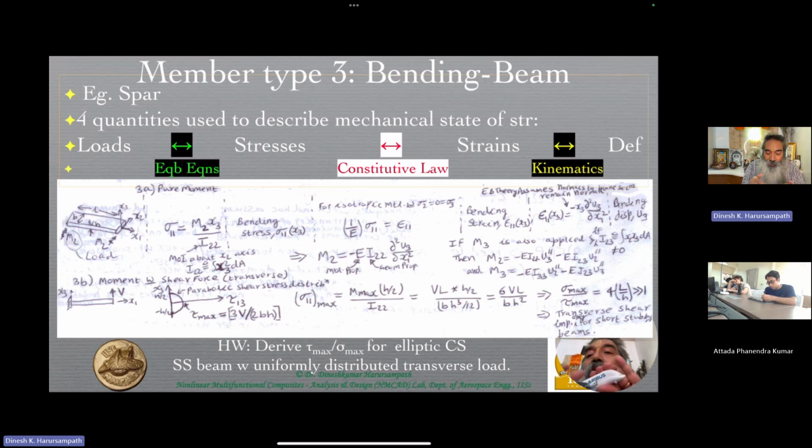And so you will have, of course, depending upon whether there is a sweep, sometimes we might introduce a coordinate system which is along the sweep angle, and therefore it may not even be an orthogonal coordinate system, because remember, one axis is along the fuselage, the other axis is along the sweep angle, so they are not making 0 degrees, but neither are they making 90 degrees. So in other words, you can have a set of axes which are not mutually orthogonal to each other, which might be actually convenient in many cases where you have a swept wing. So things become a little more complicated, but it's more of transformations that we need to understand.